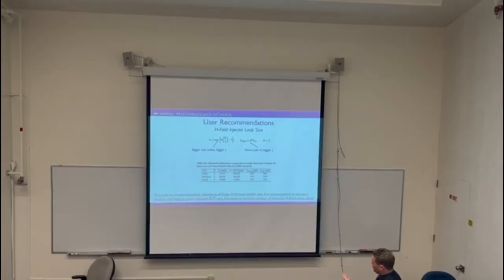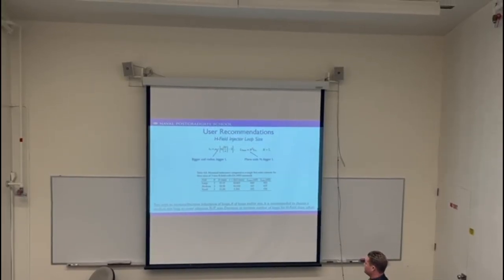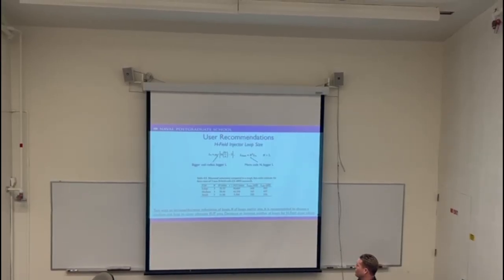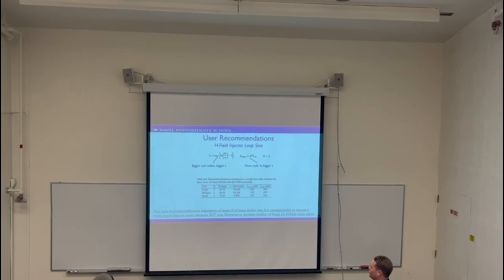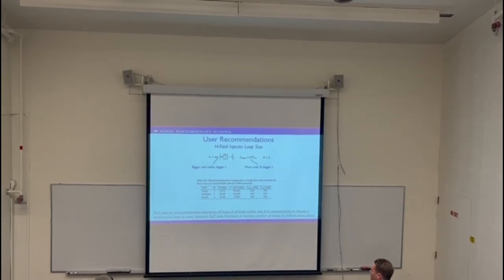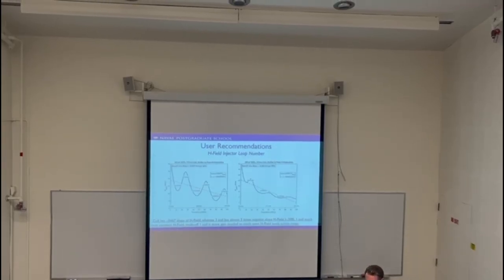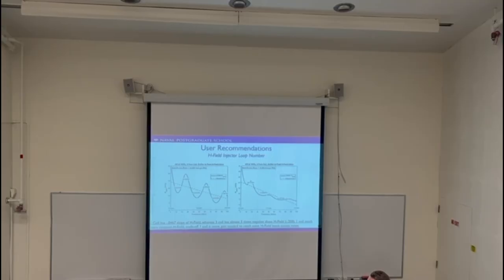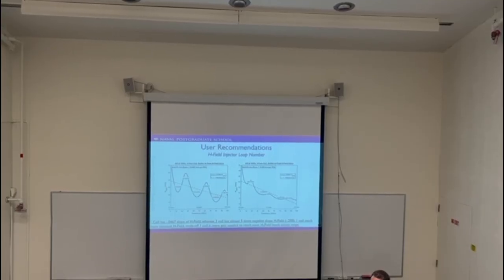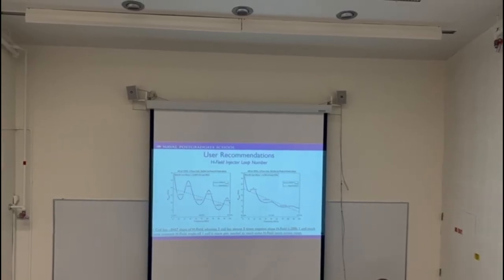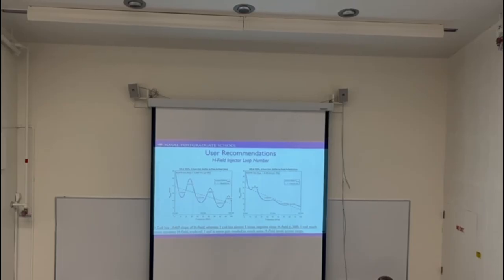So some of the things, again, we went into this loop size discussion earlier and its effect. Loop size and number of coils effect on inductance here. So again, increase the diameter, more inductance, increase the number of coils, more inductance. But is there a trade-off there? Obviously, more inductance might do something. Well, from Professor Sharif's class, I knew quite a lot about cutoff frequencies and getting to that negative 20 dB per decade section of your transfer function. And certainly with the 3-turn coil at a higher inductance, right? We knew the 3 turns going to have more inductance. So that cutoff frequency is going to actually happen at a much lower frequency. You can see here, as I talk this out, I literally...